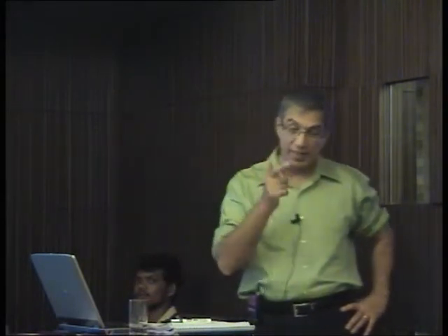No, you're still getting torque, just less. Let's say 10 amps gives me 10 Newton meters, 20 amps give me 20 Newton meters, 30 amps give me 28, 40 amps give me 35. It's not full saturation. It's between linearity and saturation.